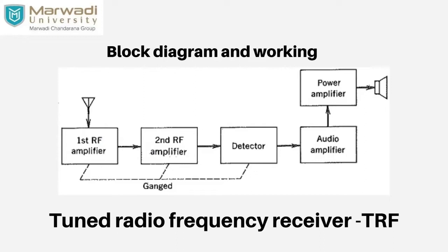From that, whatever frequency is useful for the receiver side, or what frequency we want, will be detected or demodulated by the detector from all other frequencies. As we know, the antenna will not receive only one frequency from the environment, so the detector will allow only one frequency or a nearby value of those frequencies.